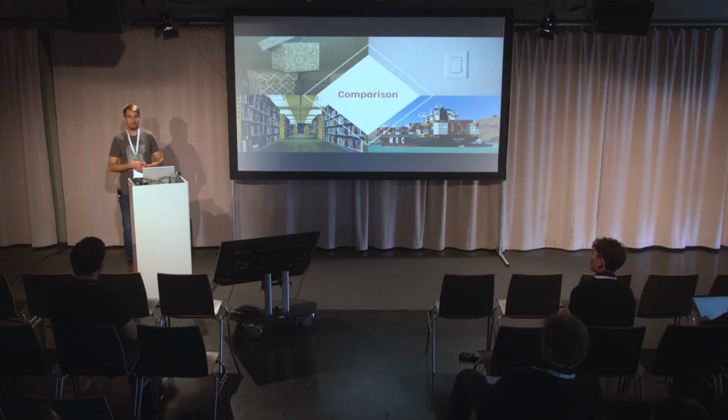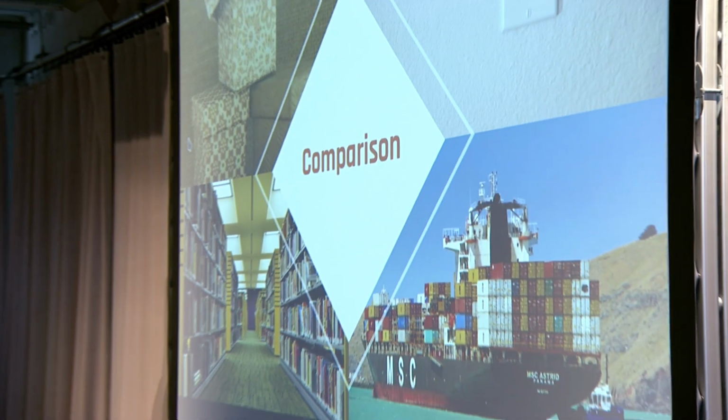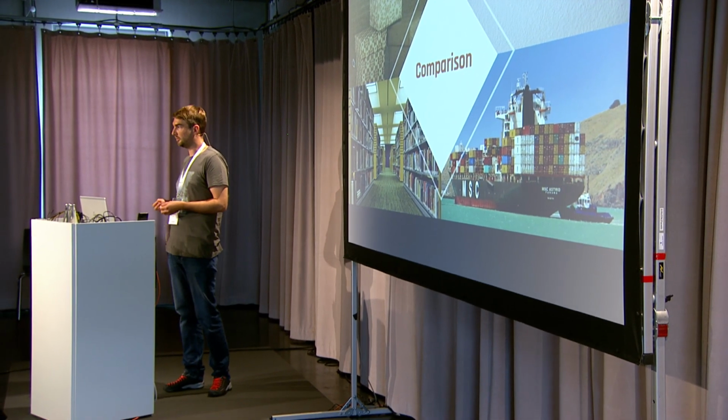Then what is the outcome of this whole presentation? So where should you use packages? The best thing is don't use them for embedded devices. If you want to use them anyways, then really only use them in fields where you know you only want to replace the application and you don't want to do full system updates. And if you normally know that it's a service technician which will install it, so that can be a device which is not connected to the internet, and someone will go to the device and just do some manual steps.